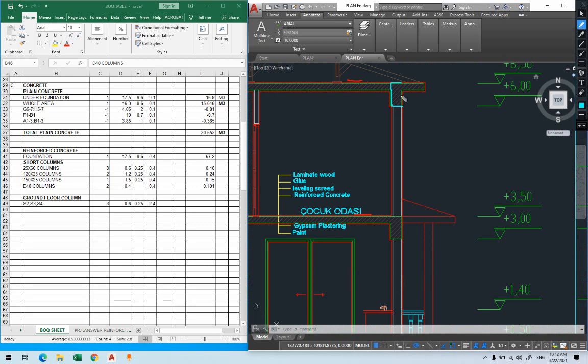because when the beams are given to us, the dimension of the beams, we can just take the total height of the beam. Out of this, we can get the height of the column. We said another information required, we have to know how many beams are coming over the column, and we have to take the deepest beam in order to calculate the height of the column.